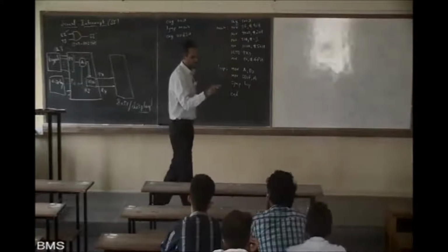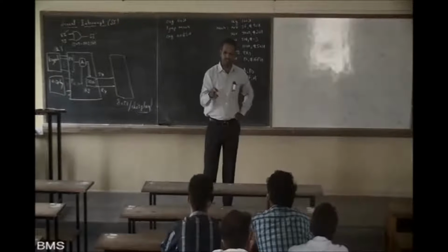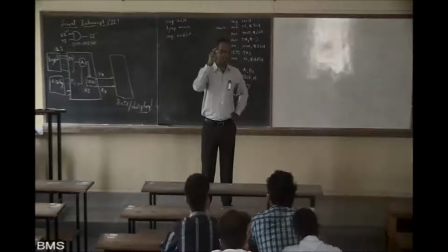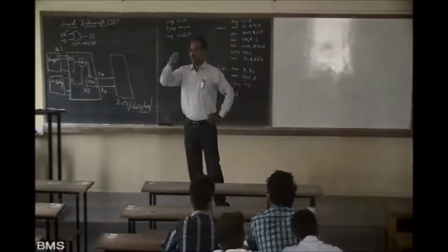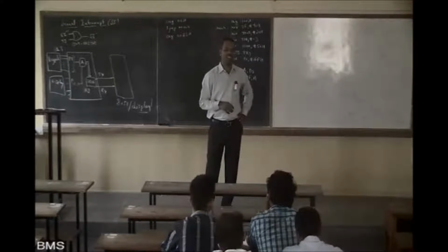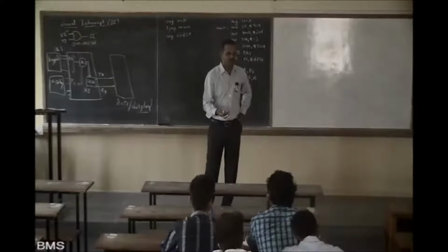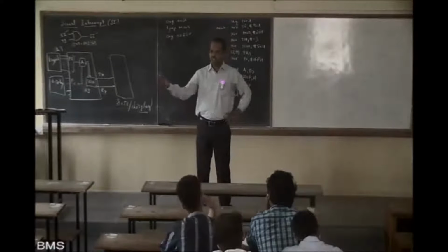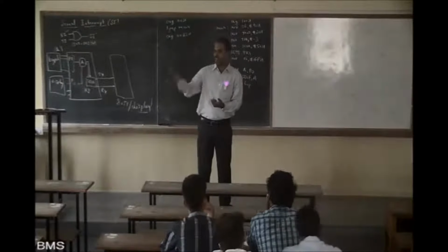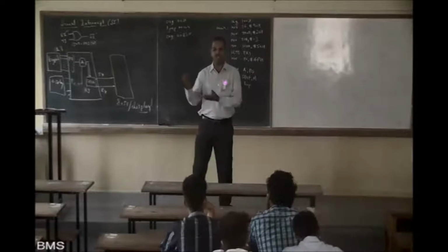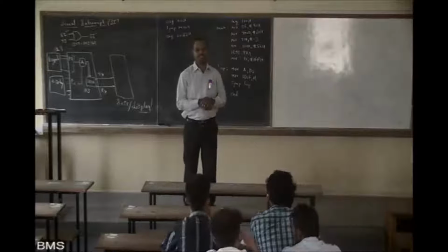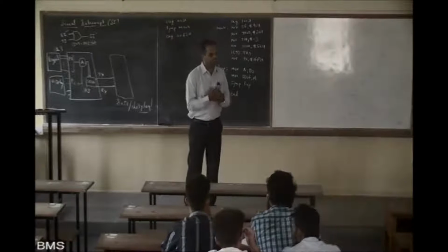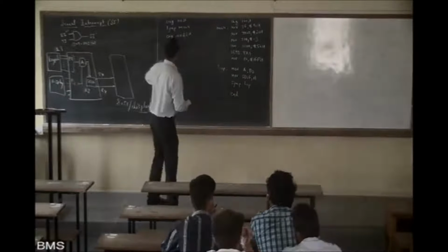Interrupt in service flags: we said RETI will clear all interrupt in service flags. But it will not clear RI and TI, because it does not know whether the interrupt has been called from TI or RI. It does not know which one to clear. So these flags have to be cleared manually. Is it clear? Right? Done.